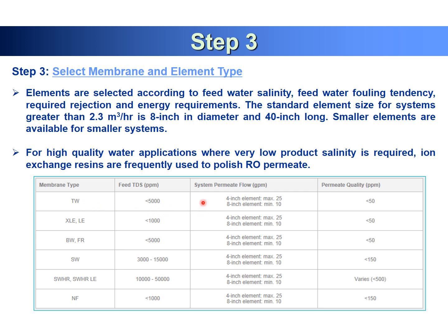Also depending on your water flow rate. If you have less than 2.3 cubic meter per hour, we can select 4-inch element, and more than 2.3, 8-inch element.